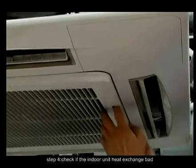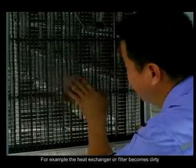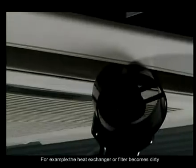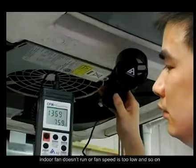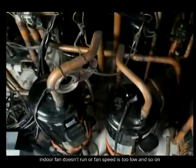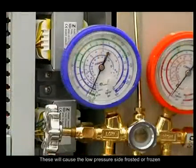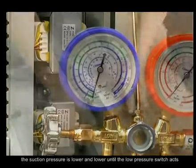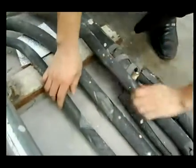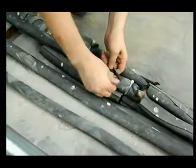Step 4. Check if the indoor unit heat exchange is bad. For example, the heat exchanger or filter becomes dirty, the resistance of the air outlet is too big, the indoor fan doesn't run, or the fan speed is too low, and so on. These will cause the low pressure side to be frosted or frozen. The suction pressure gets lower and lower until the low pressure switch acts. If it exists, please check and exclude the malfunction.